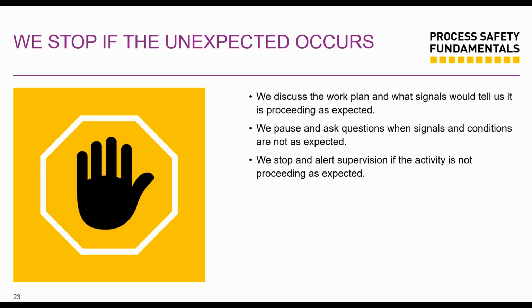Maybe you should stop and immediately roll back what you're doing, or you're having a pigging event. You're doing a pigging activity, and you see a pressure spike, and you say, hey, maybe I should just continue. Maybe you should stop, because it could indicate that you're going to have a line rupture.